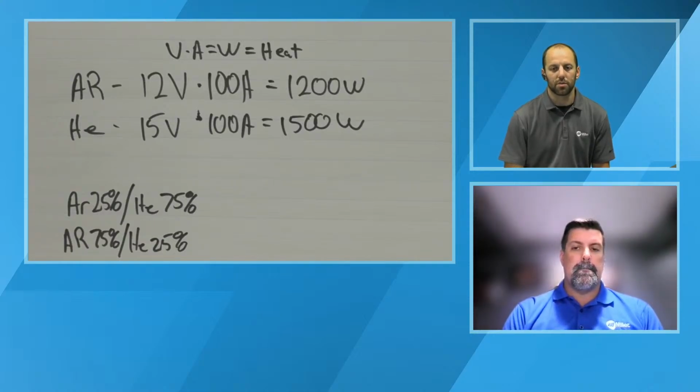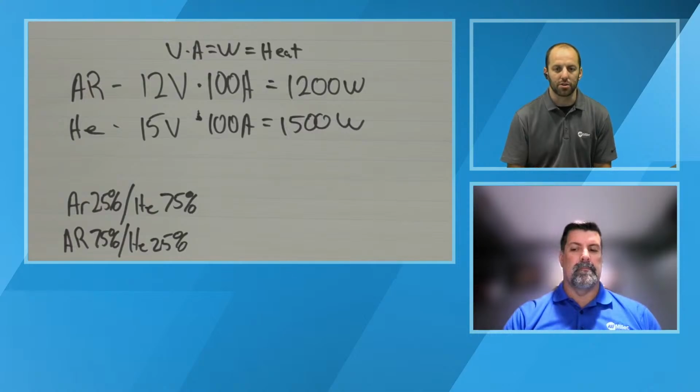Yeah, so essentially what's happening, if your tungsten is splitting or getting what I call crowning, or those little nodes on the end of it, is your tungsten is starting to degrade and it's getting overheated for the application. So if you're seeing that, you may want to consider doing that pre-balling like we talked about, or you likely need to bump up to the next size tungsten diameter for your application.